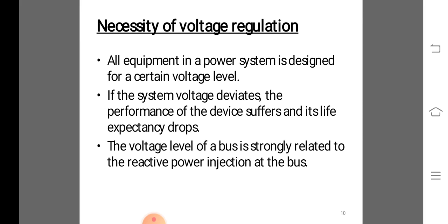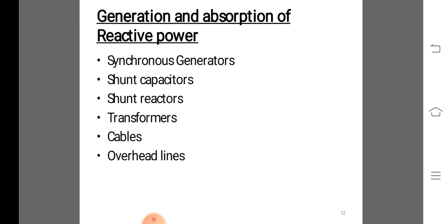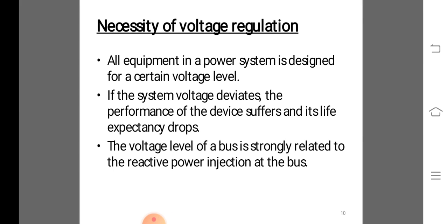The generator field can be represented by a block with the transfer function Kf/(1+sTf). The total transfer function ΔV/ΔVref is equal to G(s)/(1+G(s)). The stabilizing compensator is used to improve the dynamic response of the exciter. The input to this block is the exciter voltage and the output is a stabilizing feedback signal to reduce the excessive overshoot.